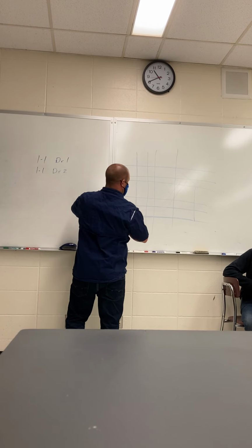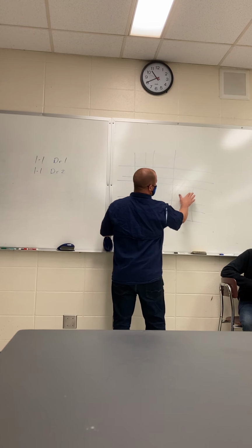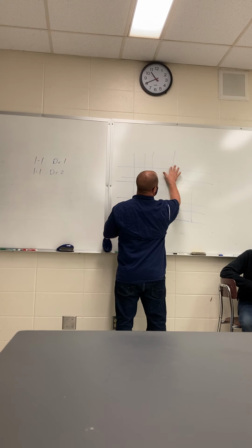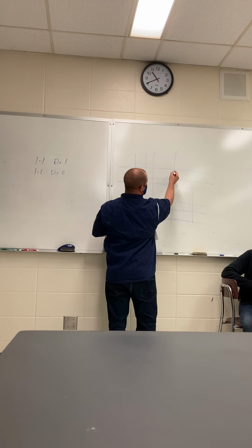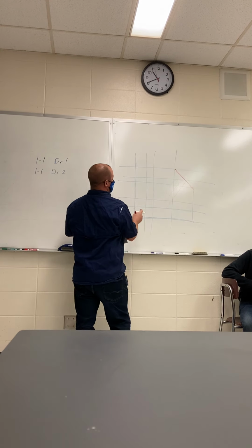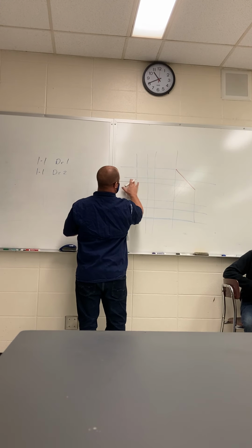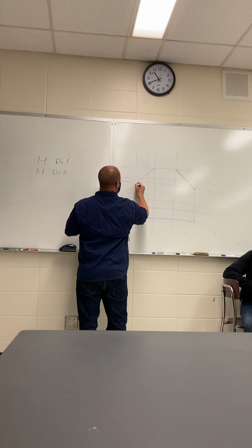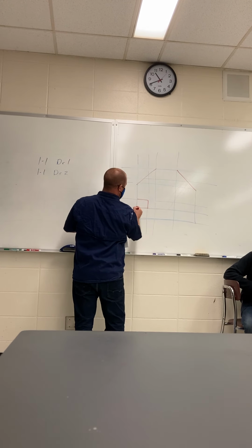And then you can use your trim command, and you can trim this off, say there, and here. Trim that off, that would become that line. You can trim off, say, here, and there. You could trim out what you don't need there, thus creating this.